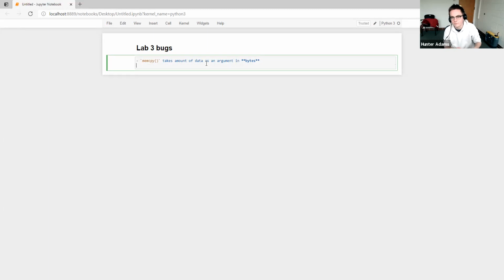That was one bug. It took us a little while to track that down. The other one, this one's a little bit more subtle, is that a number of you have encountered this issue where you start playing a sound into the PIC32 and it starts resetting over and over and over again. That can be a symptom of a number of different things. In previous labs, that's been a symptom of dividing by 0. Bruce made a list of other stuff that can cause persistent resets.